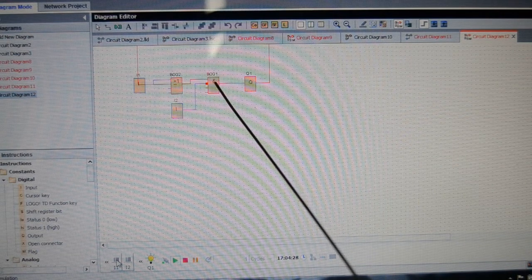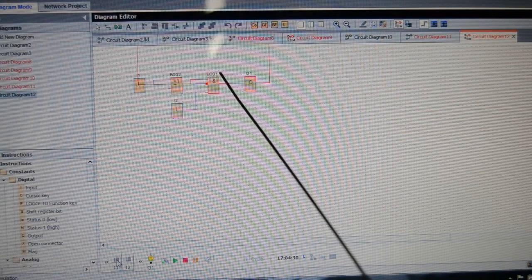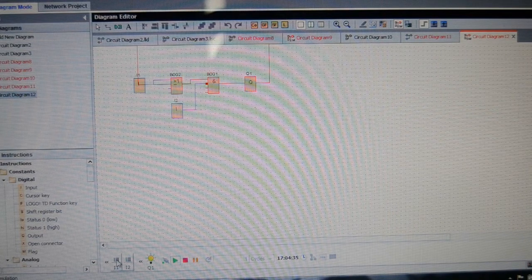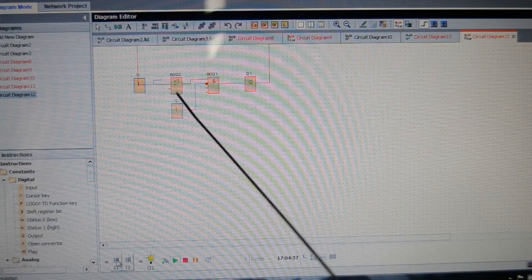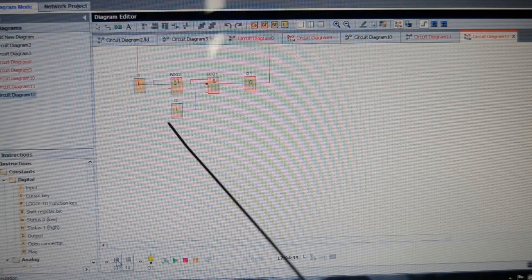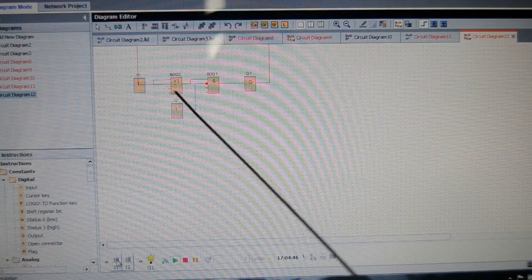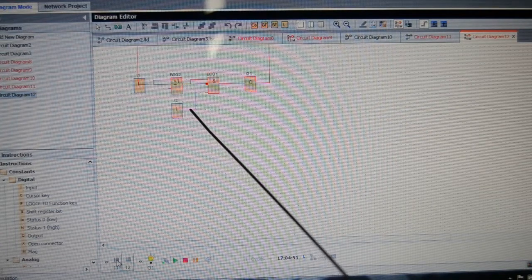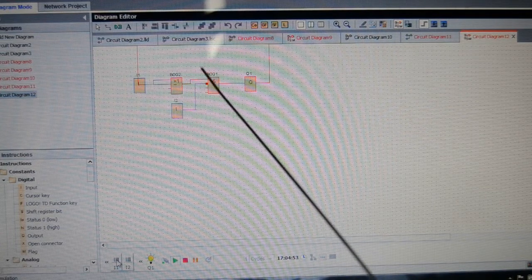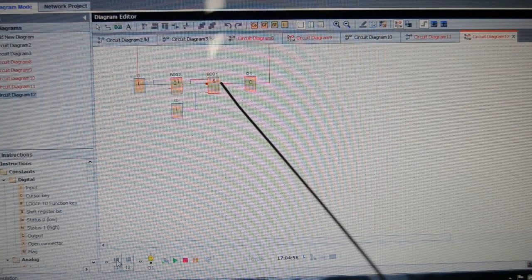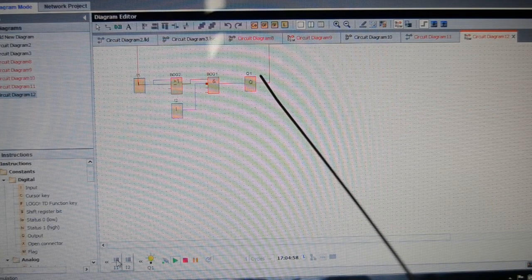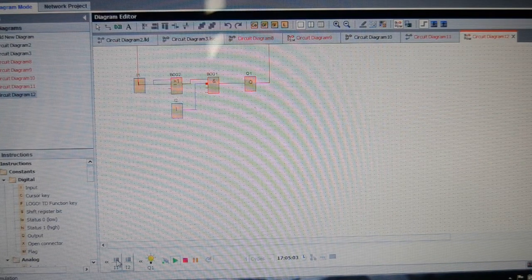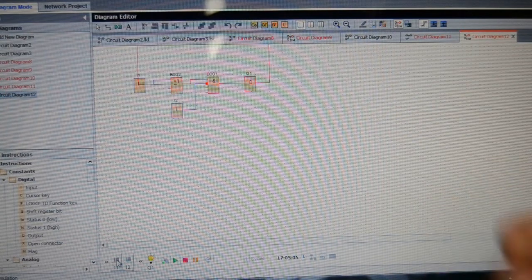Now the AND gate here requires 2 sets of true logic to be operative, but because this input 2 is a normally closed switch, it's actually getting that. Even though it's not highlighted as red, because it's normally closed, there is a flow of logic coming through here, which means because this AND gate is true, the output is therefore on, which feeds back into the circuit, and we have our continuous loop, which is keeping the setup running constantly.